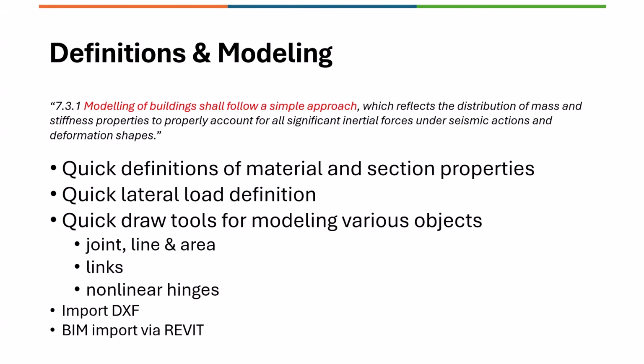We also have link. A link is a special element that can be used to model highly nonlinear behaving elements, like force deformation behaviors such as dampers, isolators, right, that can be modeled using the links. And then to study the performances or the responses in the nonlinear range, we have nonlinear